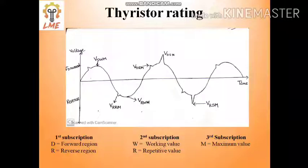The full details of the rating are on the basis of the subscripts. Okay, if the first subscript is D, that denotes the forward region. If the first subscript is R, that is known as the reverse region. If the second subscript is W, then that is known as the working value. If it is R, that is known as the repetitive value. If the third subscript is M, that is known as the maximum value. So this is the first subscript, second subscript and third subscript.